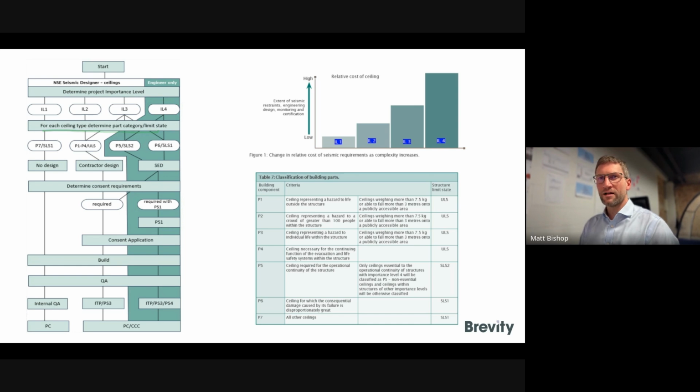and we're talking about the individual ceiling rooms, if you go strictly by the part category, that small ceiling in that storage room doesn't need a seismic restraint design. So if it was coming to the point of value engineering, say, as you're going through the project, and for whatever reason an engineer had spec'd 2 braces into that storage room, a contractor would be well placed to argue the fact that maybe that was an over design. Probably was an over design.